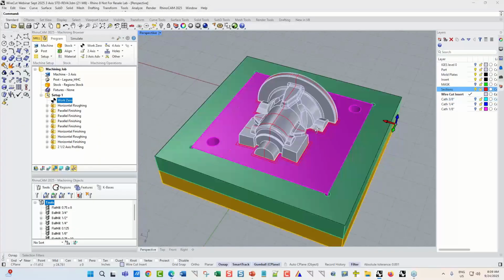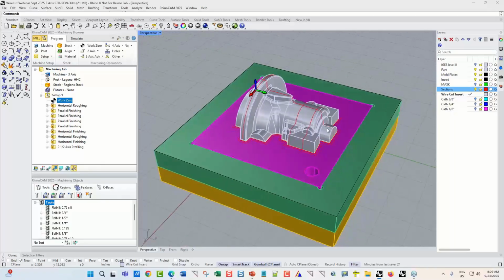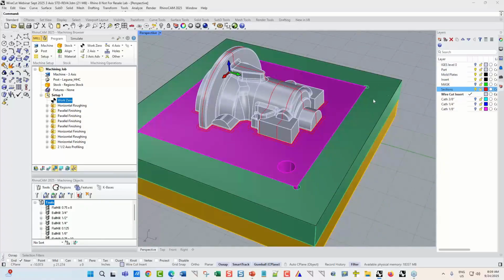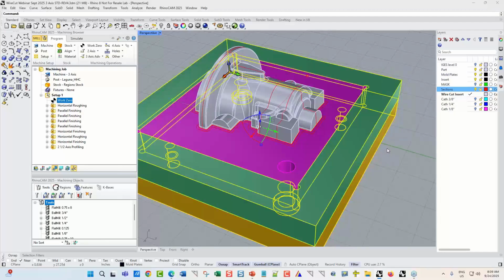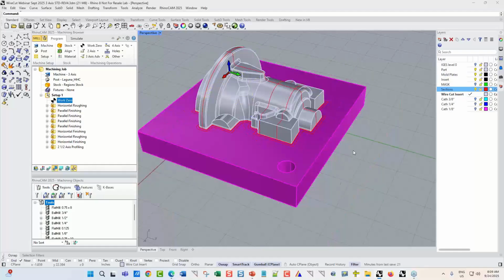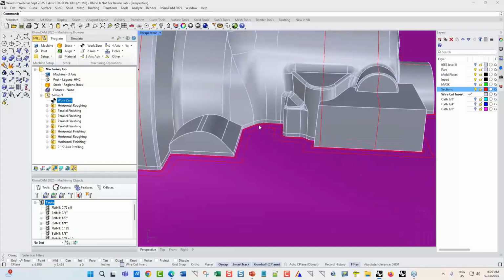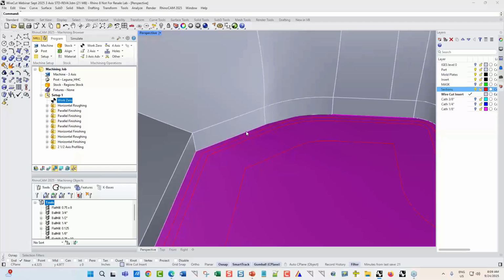Now you see that we have the same core insert. We have the insert plate with the core surfaces on top. We have the mold plates here, and I'm just going to hide those. Okay, so what will most likely happen in a production environment for this mold insert is that you really want to get a sharp edge there, because that's what the part requires at the parting plane or the parting line. So you really need to maintain that sharp edge.